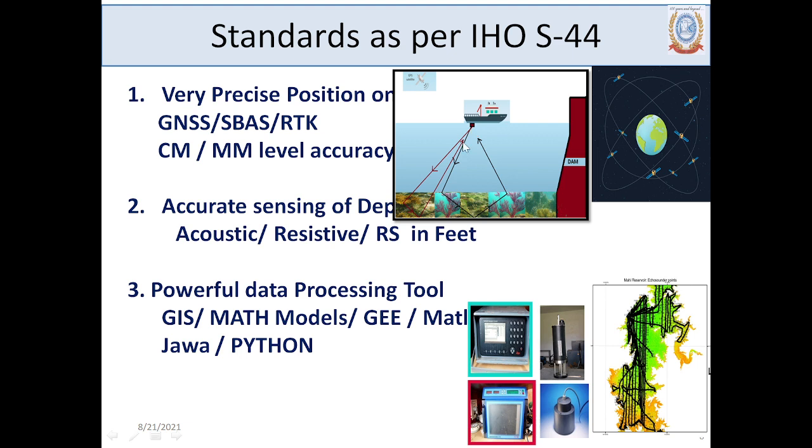The original data will go through a lot of reflections. Now what the board measures is the time taken for the sound to be ejected at this point until it reaches back. So what you are getting is the time taken divided by the speed of sound will give you the depth. Now the boat movement, all those things have to be compensated for your quality measurement, and the bottom submerged materials are also to be taken care of, otherwise you will be getting multiple echoes.